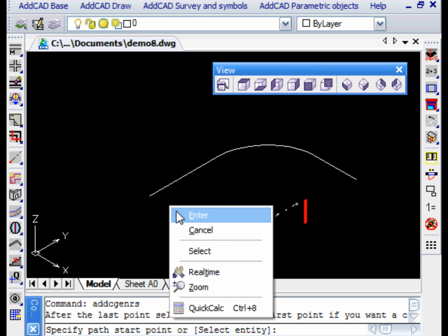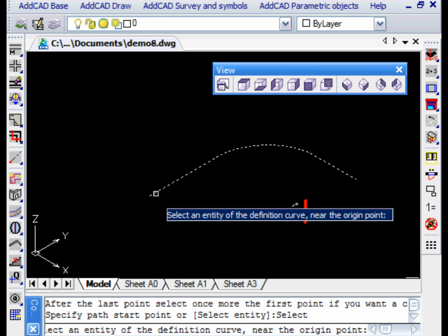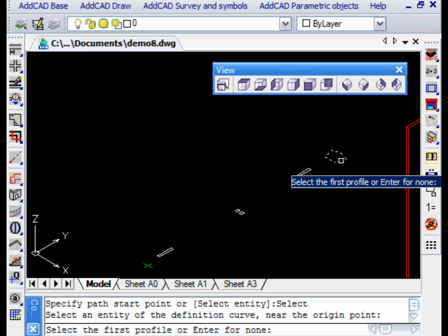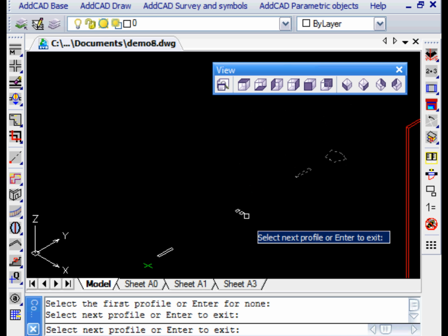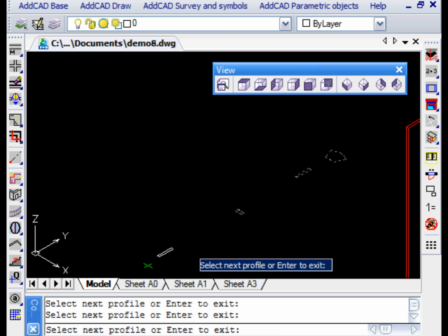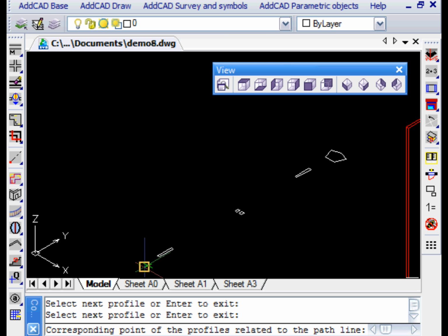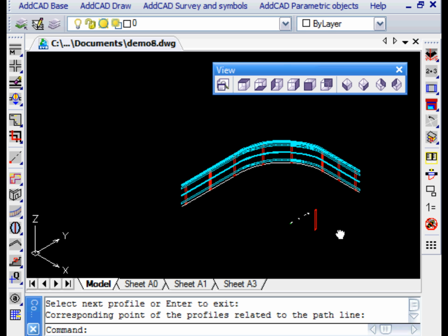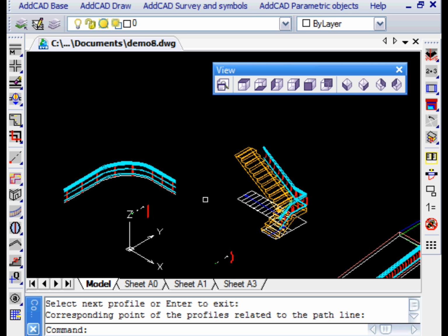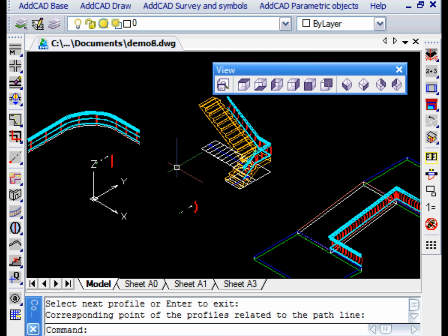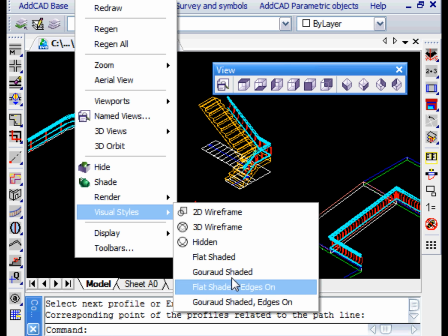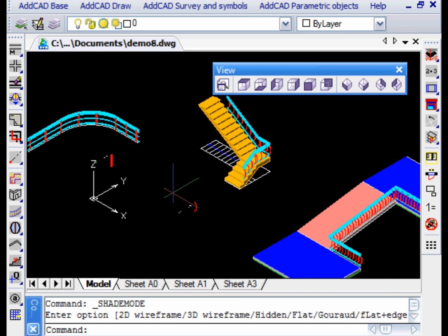The selected point on the polyline also identifies the direction of development of the fence, that is important to suitably rotate the vertical elements on the right or the left and for the position of the profiles. As in the previous examples, we finish the input of the command with the selection of the profiles and the reference point. Note that the number of profiles is not limited and they also might not be present at all.